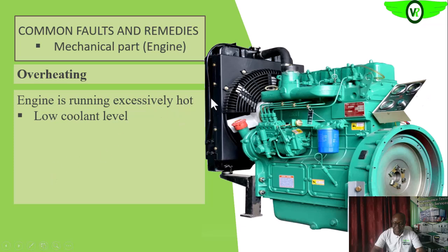If the quantity of water that you need to go through the generator is lower than what is required or what is designed for, we can experience such. So if you notice that that is the case, you top up the coolant in the radiator.